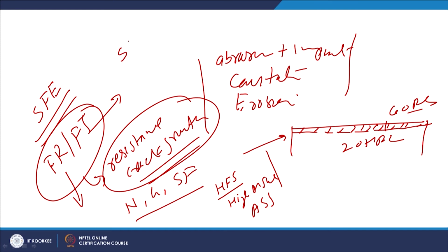Such conditions exist in surface fatigue, cavitation, and solid particle erosion. These are the conditions where fatigue resistance and fracture toughness really play a good role, because in all these cases the crack nucleation and its growth followed by coalescence will lead to the removal of the material in the form of fine chips. So, both these properties are of importance.